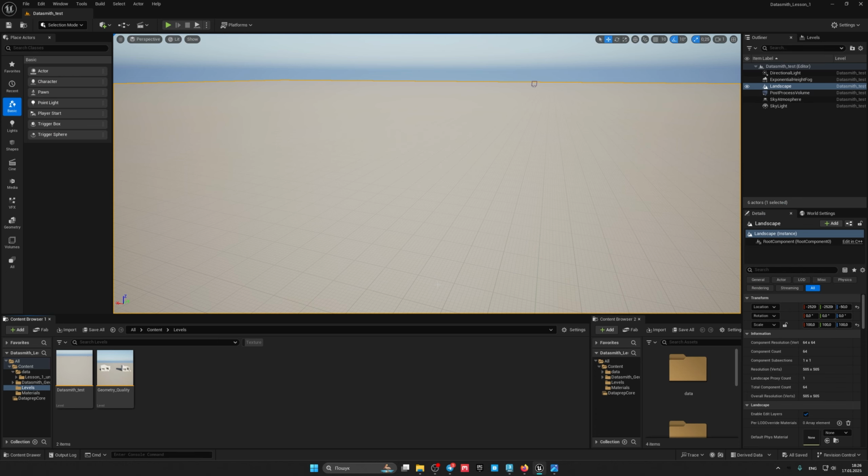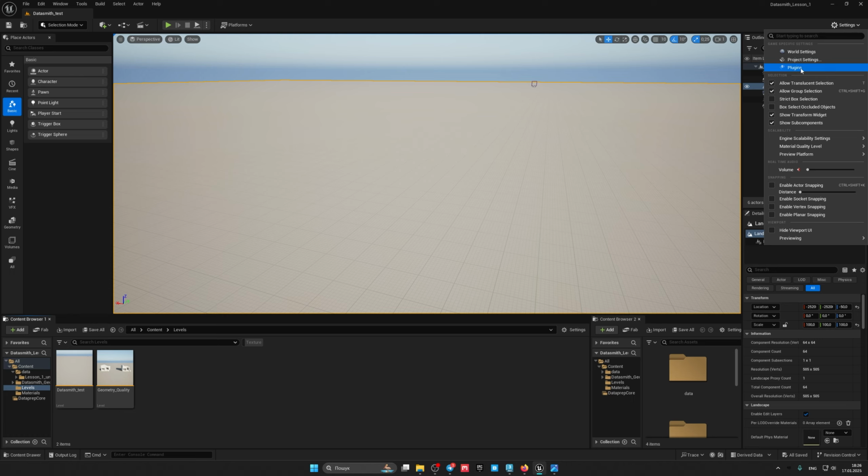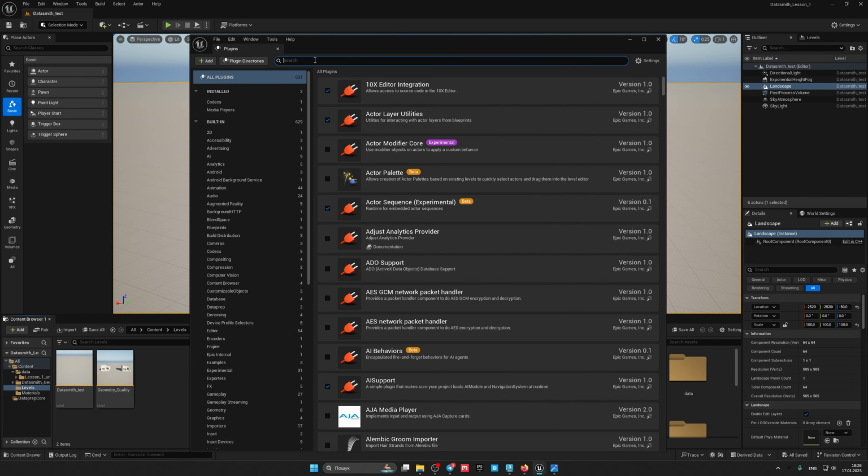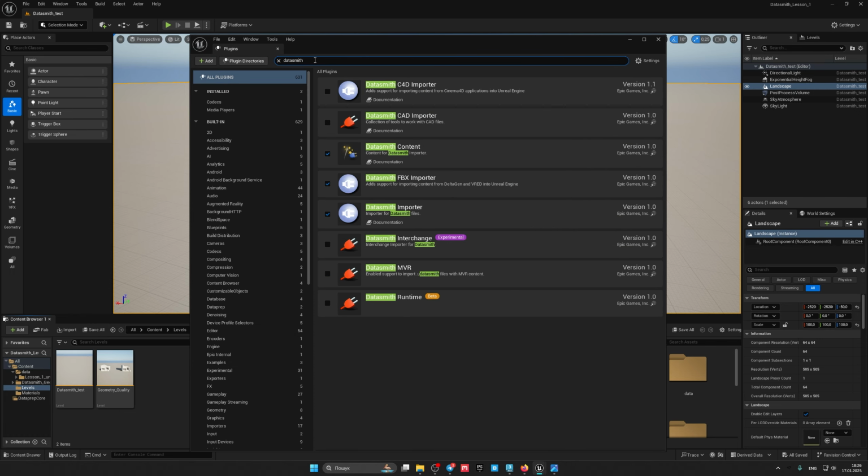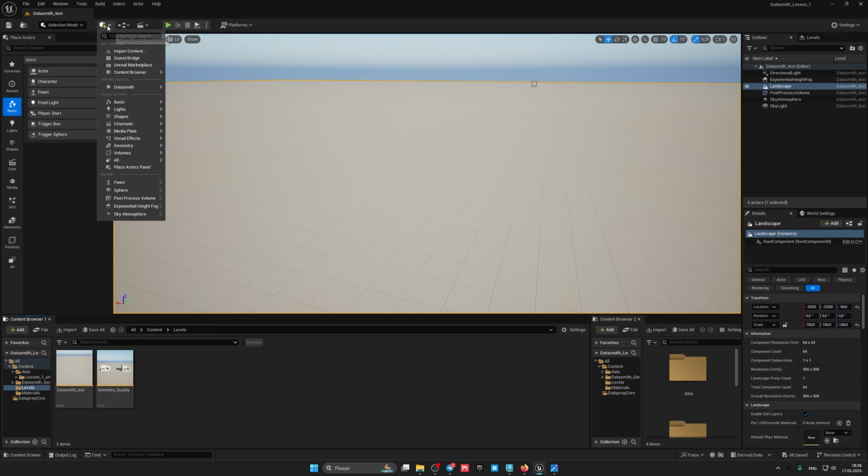We switch to Unreal, and in Unreal, to enable the Datasmith plugin, we need to go to Settings, Plugins, and find Data, and enable this Datasmith FBX importer and Datasmith importer. Check two boxes and here you will see a message: restart your Unreal. Agree, click, and after restarting, Datasmith will appear here in the panel. Add to project. And here we have the Direct Link import.